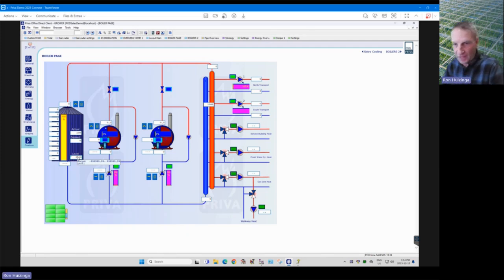The reason for that is, if you have a leak in the greenhouse or a leak somewhere and the tank is dropping in water, then we can give an alarm to say the water level has dropped too low, you must have something wrong, you better be careful that you don't have a leak somewhere. So you can have multiple alarms, but let's say two alarms.